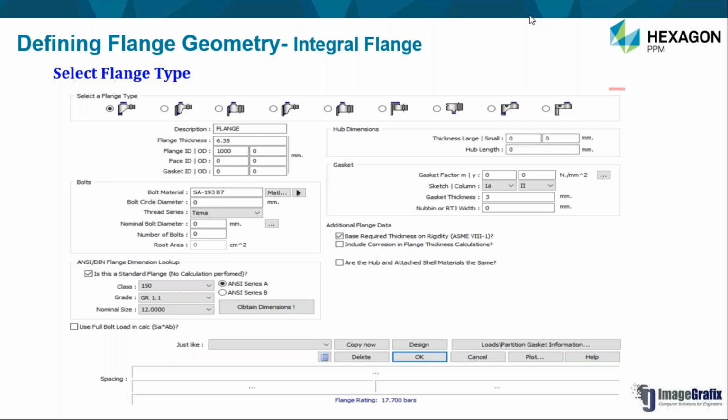If the stresses are lesser than your allowable stress and your rigidity index is lesser than 1, then whatever parameters we have selected are approved and the flange is safe. That is what we are going to check. So first we have to assume the flange parameters and then start with the flange design. So how to optimize the flange?